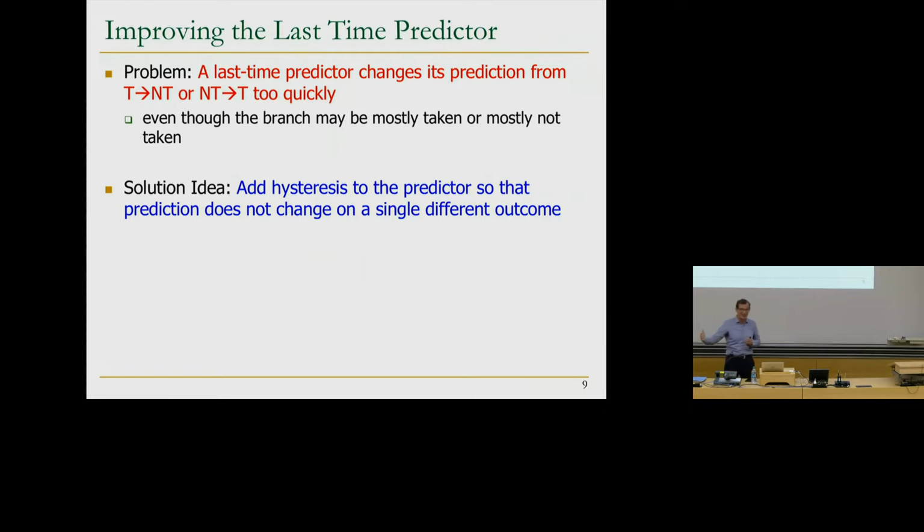its state very quickly. You may notice this in, for example, air conditioning or heating systems. Usually people, whenever they detect temperature and want to take an action based on it, add some hysteresis. For example, if you want to set the room temperature to 22 degrees Celsius, and you have a temperature sensor that detects and controls heating or cooling so that you can stay at 22 degrees Celsius, you want the control system to have some hysteresis.